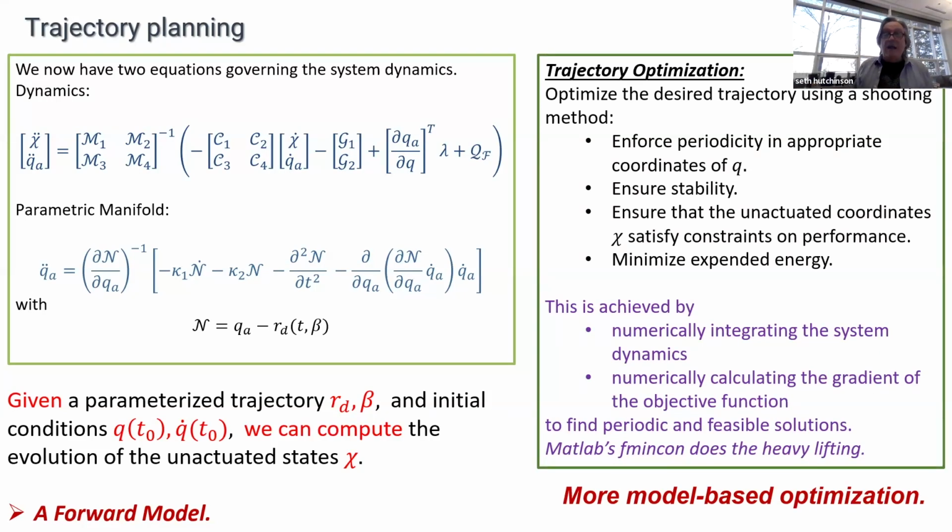And this is how we do it. Right. So we optimize, first of all, to ensure some periodic motion in some of the coordinates, particularly the flapping coordinates. We want stability. We want to make sure that you don't fall out of the sky. You don't do rolling or pitching. Yaw is not particularly good, but it doesn't have the same instability properties as pitching does, for example.